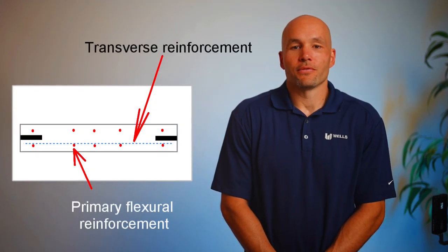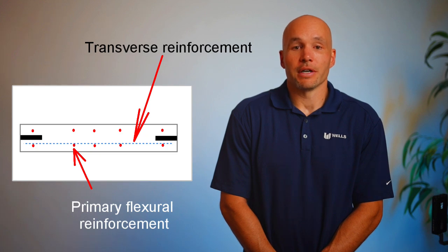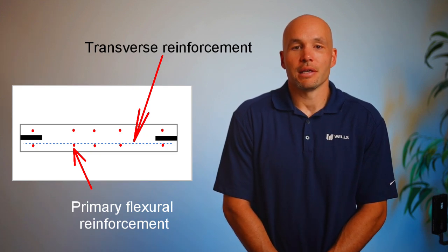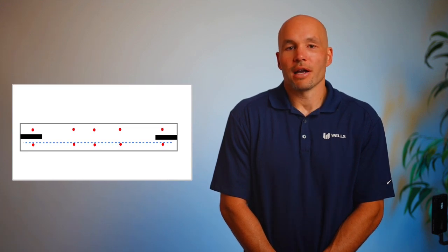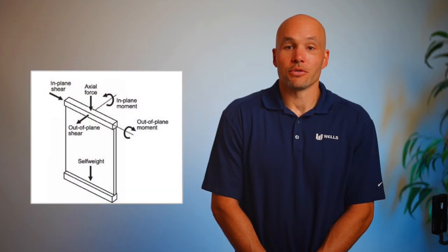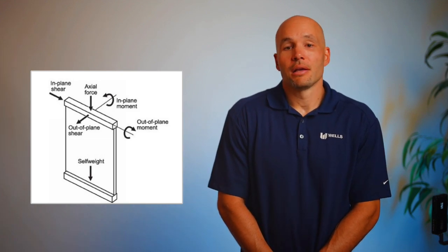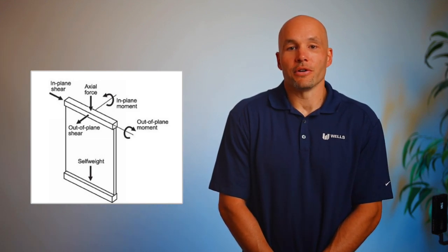Supplemental transverse reinforcement is provided at lifting devices and in other strategic locations to transfer load in the opposite direction as needed. A variety of connections exist within the body of the panel to support and connect other precast elements and materials. Wall panels can transfer a wide variety of loads in multiple directions simultaneously, therefore proper analysis of the various load cases is important.